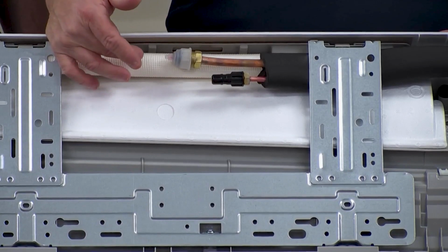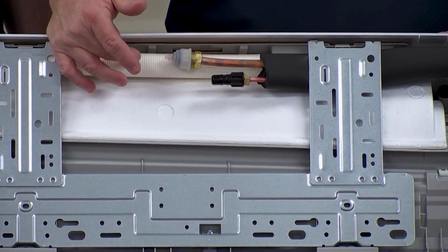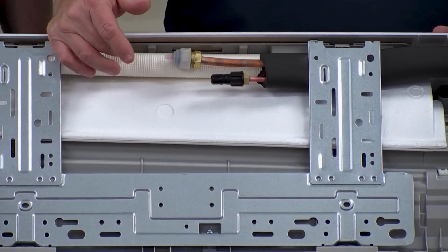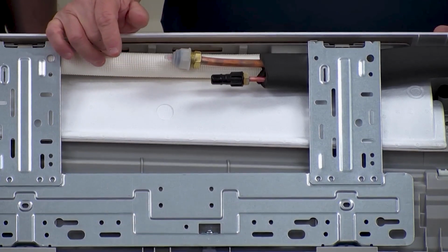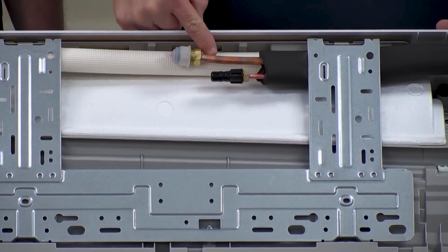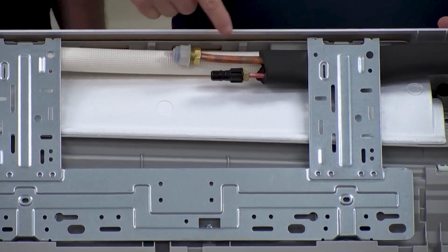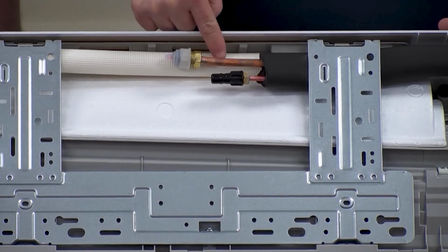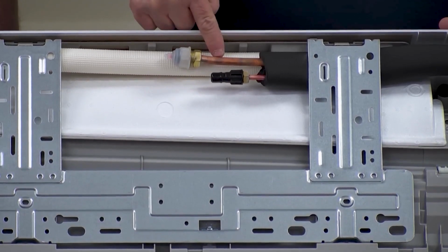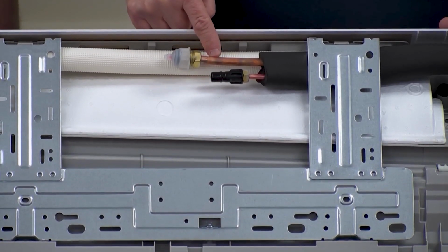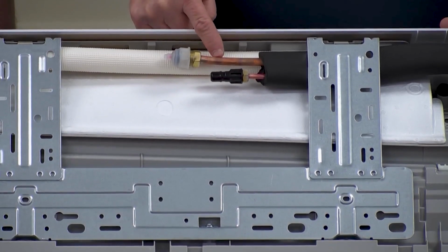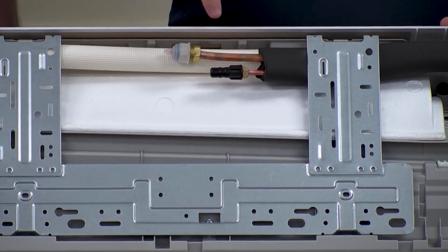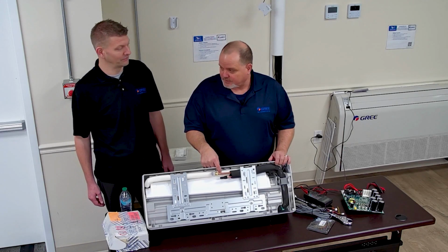That is going to be 3/8, United States measurement in inches. That pipe is metric. That's correct. So your press fit is not going to fit that pipe properly, and you're probably not going to get the proper seal on that metric pipe. It could leak eventually, even if it doesn't right then.